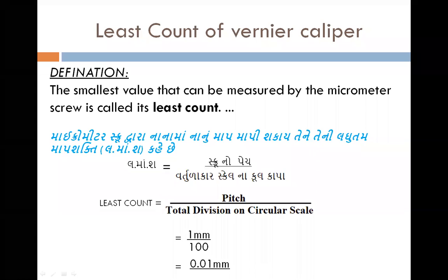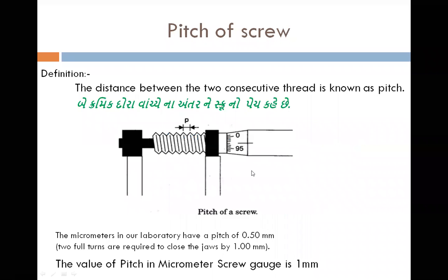Okay. In case of centimeter, I can write the same as 0.001 cm. That is the least count in the case of centimeter. If I measure it or I want to get the readings in centimeter. But basically, the apparatus main scale is always in mm. So you get the answers also in mm only. Yes, there are 100 divisions which are shown here.